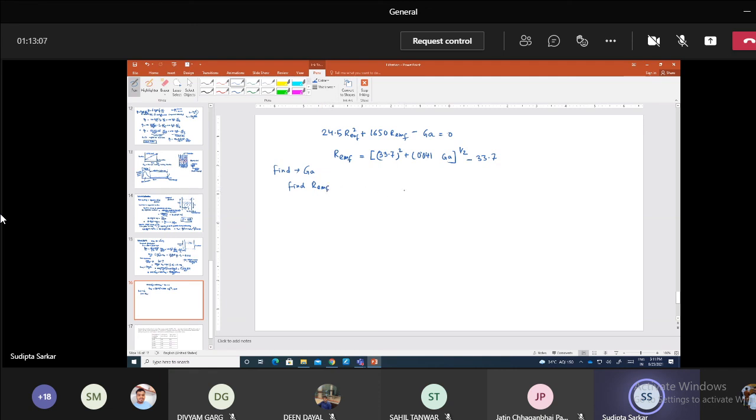Okay, and when you know the value of REMF, REMF is nothing but rho VMF into d by mu. In this, you know rho, you know d, you know mu, but the only thing you do not know is VMF. So when you know REMF, you can find VMF equals mu REMF divided by rho d. So this is how you can find out the VMF, the minimum velocity of fluidization. The design value is normally given as 1.35 times VMF.